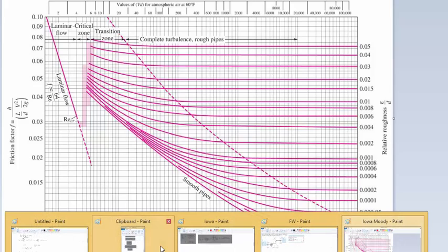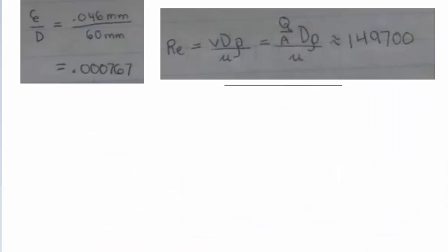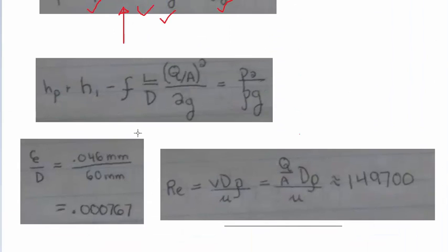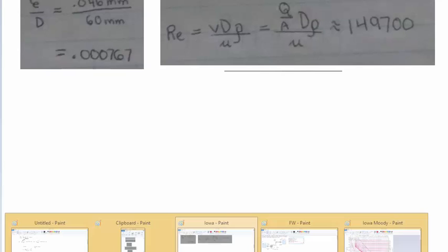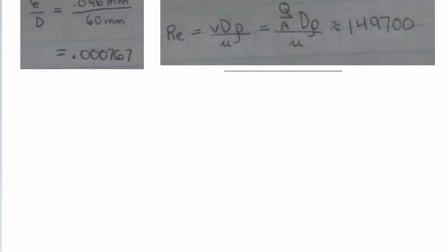So to solve the problem, you would go back here, say that the friction factor is 0.02, plug that in right here, and then everything else you know. So to finish up, to find the power of that pump, you just say the power is going to be, if you remember from our energy video, just this, which is what it typically is.